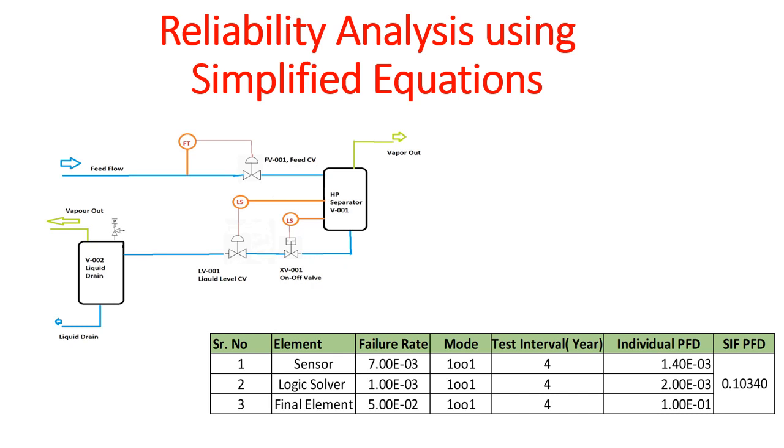In our previous video, we discussed that there are various techniques for reliability analysis of a particular SIF, for example, Markov analysis, parts count technique, etc. Another technique is the simplified equation, which is the most simple and easy method and does not specifically need any tool for analysis. You can use your own Excel, where you can give the formulae and do your analysis on your own.